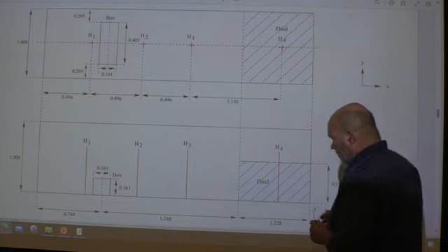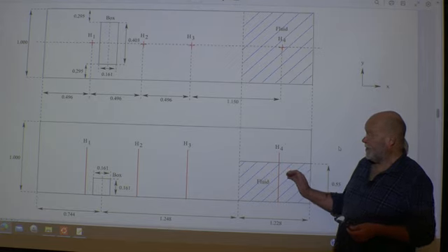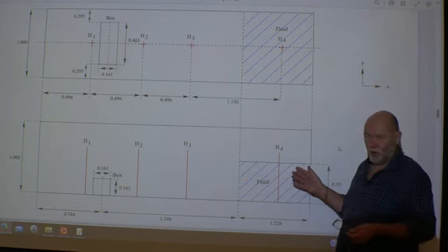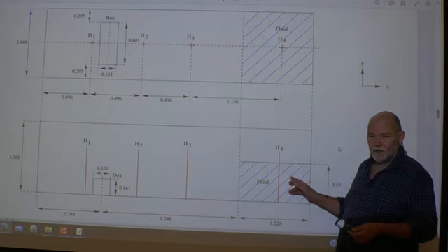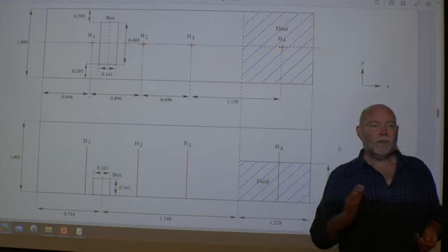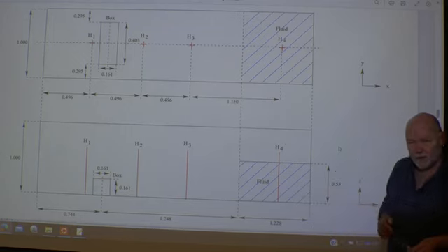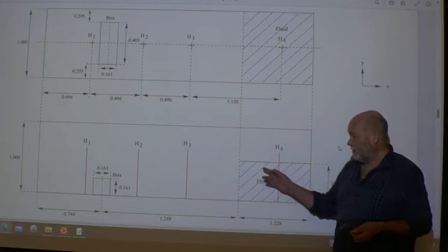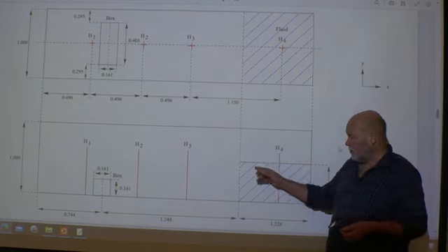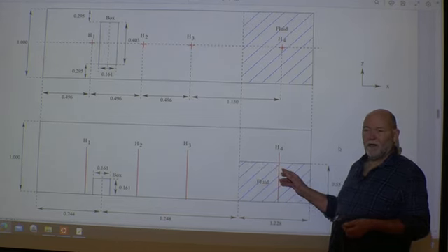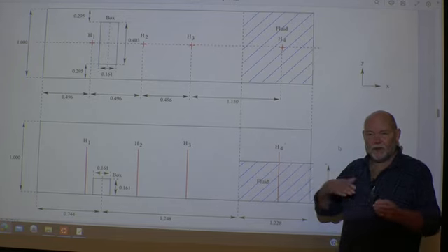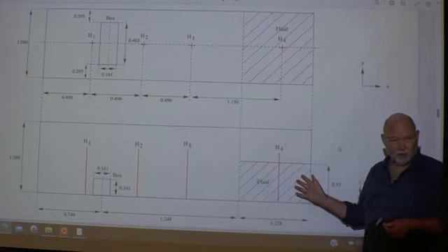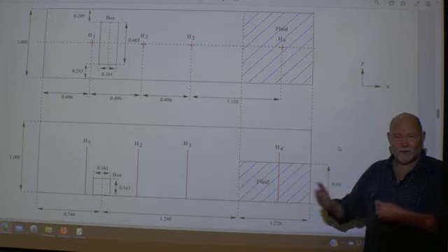And initially, when you are using, say, interFoam, you set up this region filled with water. The volume of this region should be the same in all 3 meshes. Because when you're using the script setFields, it's the one that puts initially 1 for water and 0 for air. It can only do it with 1s and 0s. You don't have anything in between. Meaning, if this volume doesn't match your mesh, then you're going to have different volumes for the 3 different meshes.